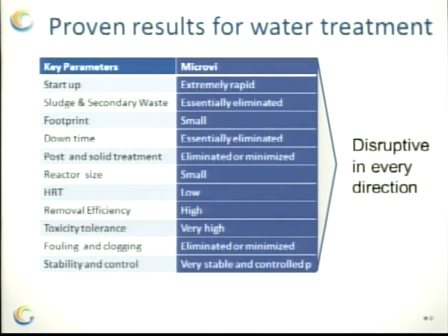We then take that pure culture or biomass and run it through a manufacturing process where we essentially house them inside of a biocatalyst. These biocatalysts are about 3 to 5 millimeters and spherical in shape. They're extremely porous, and they mimic the environment that these denitrifiers are used to living in. So from day one, when you load these biocatalysts in, you've got an extremely fast startup time. You've got an extremely high population of pure denitrifiers inside of your reactor, so you're not dealing with competition from other organisms that you typically would come across.